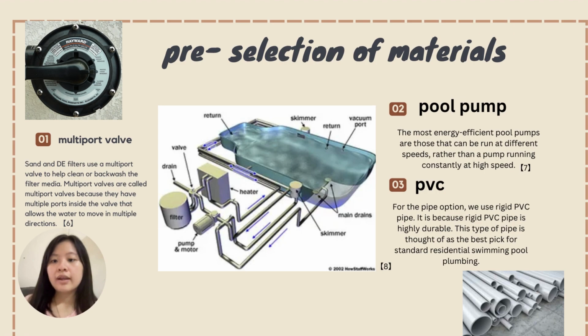It is called a multi-port valve because it has multiple ports inside that allow water to move in various directions. In the figure in the middle, you can see the valve is connected to the filter, the pump, the heater, and also the drain.